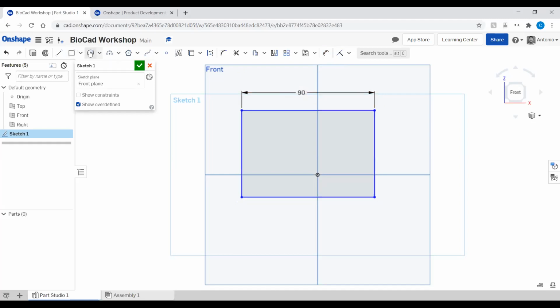And then you can also say you want to cut a little keychain. You can cut a hole right here by drawing a circle. So there's a circle menu right here. The keyboard shortcut is just C. And so there you have a finalized object that you can extrude or do something to now. And you know that it's closed, or you know that it's finished, because it's filled in with this dark gray. Only when something is filled in with dark gray is it able to be extruded from there.